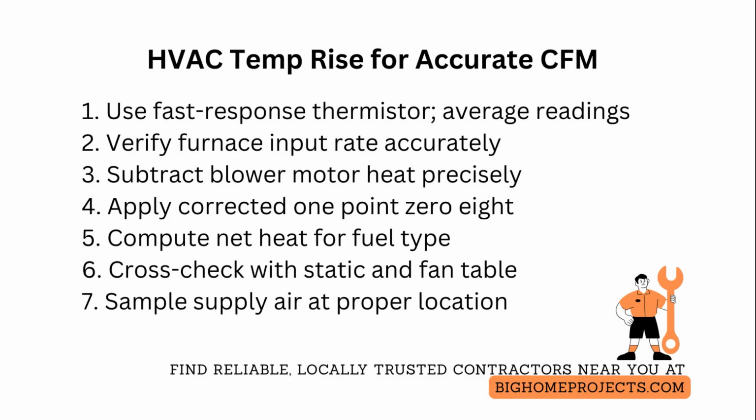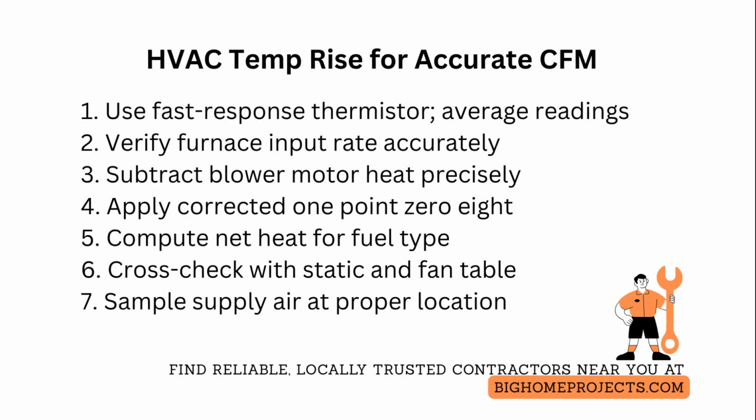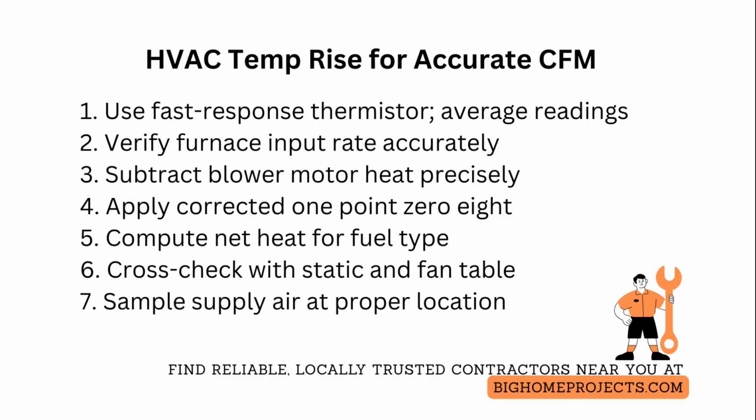Stabilize the system for at least 10 minutes at steady state firing before logging data. Short cycling or staged heating transitions will fake a drifting temperature differential. Document filter type, duct size, register's open count, and coil condition so future tests are comparable and reproducible.